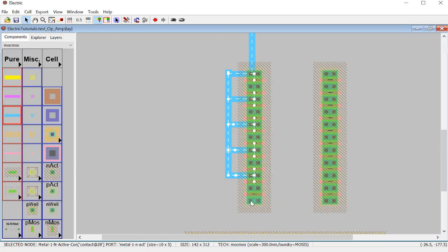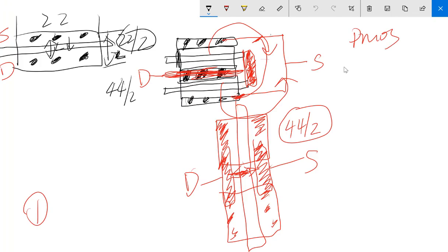The reason that if that is a drain, this has to be a drain, is we have to skip every other one to make all these ones the drain. So you can imagine that you are splitting all these transistors and rotating them and combining them together, right? We just explained that over here, right? If you forgot, you can come back here to see why this works.